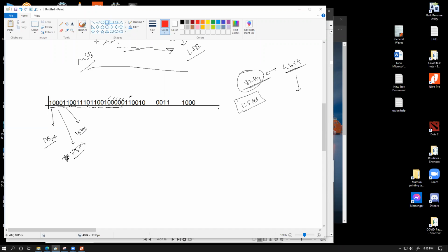Something like this. It's going to chop this data into groups of 4. So let's say this is my first decimal data, and then this is my second decimal data. Then maybe this is my third decimal data. So it's going to chop this whole series of numbers into 4 apiece, because it would know from our instruction that it is a system of 4-bit data transfer. So every data will be divided into chopping of 4. After chopping, each of these data would be converted as individual different numbers. So this will become 8, this will become 12, this will become 14, and so on. So you will basically recover the whole digital signal into its original decimal values.